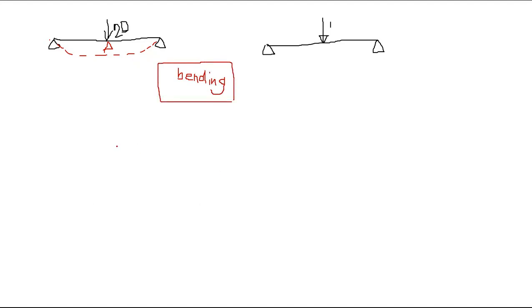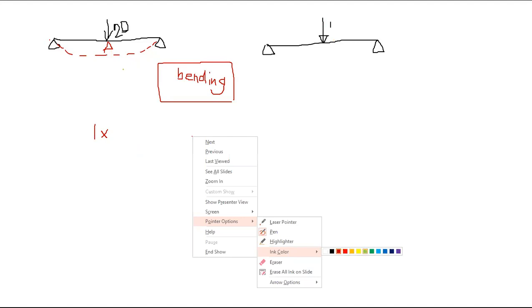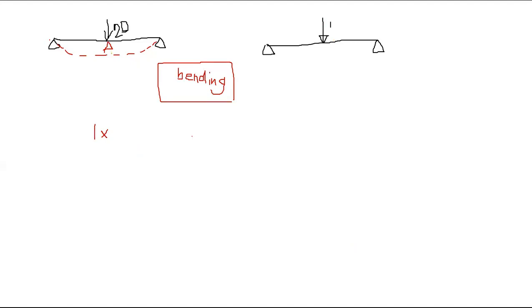So that you can write an equation. So this is the disturbance force into the actual displacement. So we know the assumption made in this complementary theory is that displacements are fixed, right? So if you apply a virtual force, very little, think about a very little force, if it is 1, then the work done by that virtual force is 1 into delta.